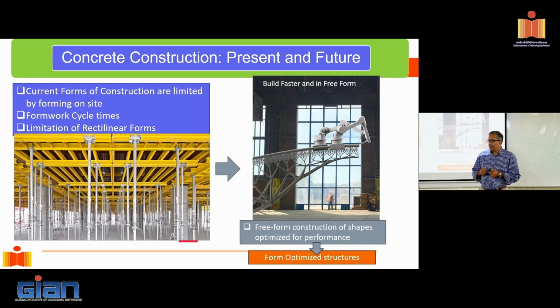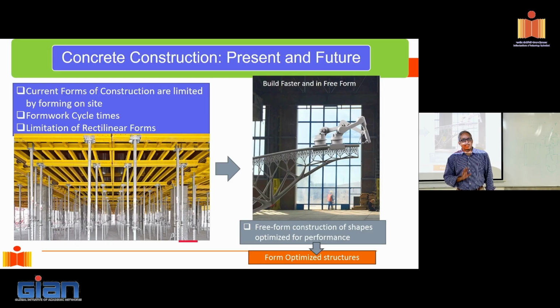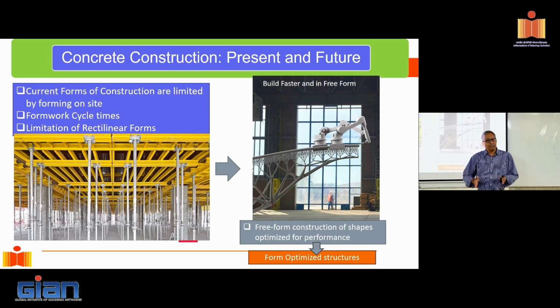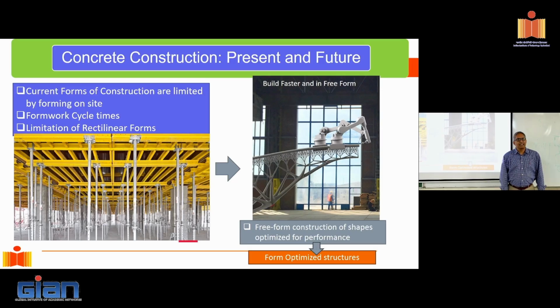Now what is happening? You basically start going down what is called a downward spiral. Now what's a downward spiral? Well, in order to support its weight, you need more material, and the material only adds more demand. Now at some point, if you follow the negative spiral, you can't even design an RC beam. And usually that break-even point is around 10 to 12 meters. You'll find that around 10 to 12 meters, if you start exceeding that, try designing an RC beam. You'll get stuck in that negative spiral. You'll not be able to design.